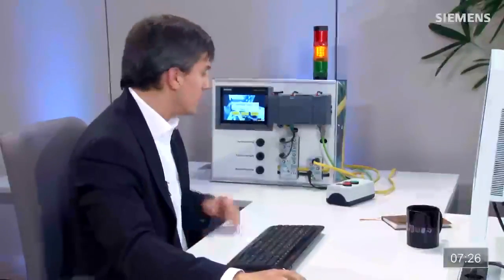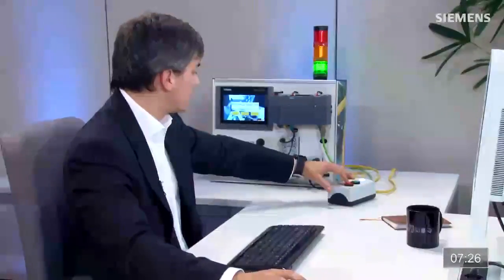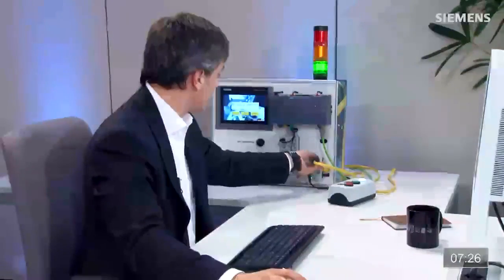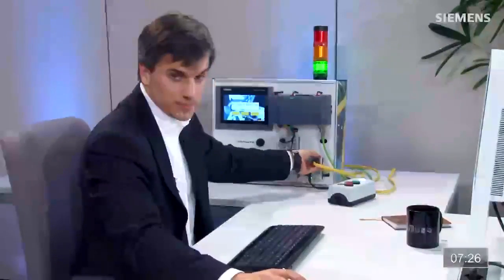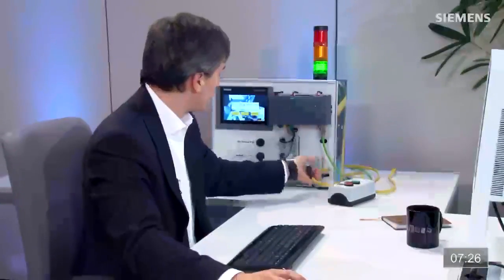All I got to do now is go here and hit the start-stop station. Everything runs the way it's supposed to. And in fact, I can go over and fault out the AS-i network. And this is the actual input for our start-stop station. It should fault. So the fault logic is working the way it should be.